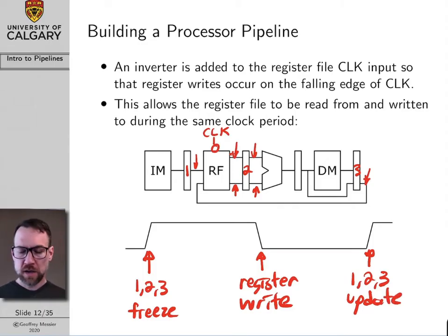And so hopefully you can see that the purpose of these pipeline registers is basically to freeze the output of each stage, allow the stages some freedom to change and update without confusing what's happening further on down the microarchitecture. And again, I'm going to be showing you more and more diagrams to show you this in different ways, so you can get used to this idea.